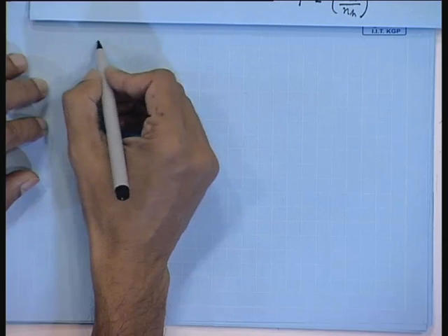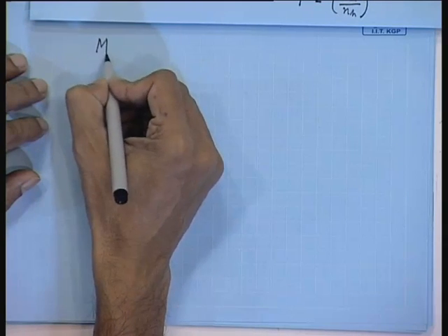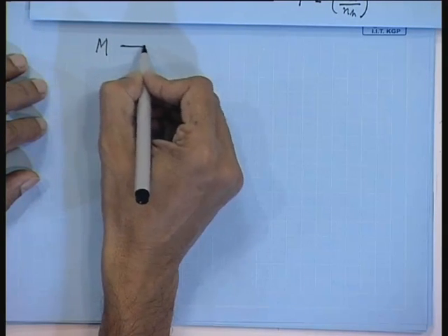Now, the reason that we have calculated Y is that sometimes they have a limit on deflection for pile. Pile deflection, there is limit, you cannot keep on deflecting the pile according to your load, otherwise it will break. So, most of the classification societies, they have a limit on Y, and from this M you can calculate, once you know the bending moment, you can calculate bending stress.